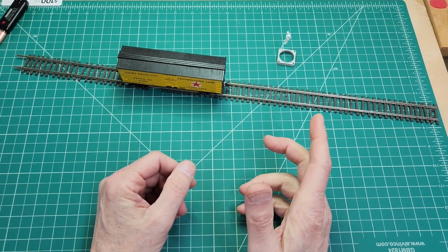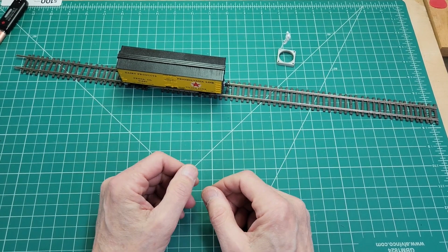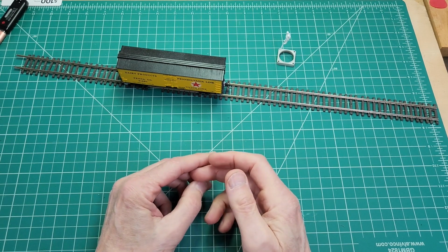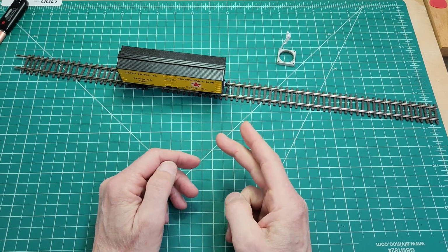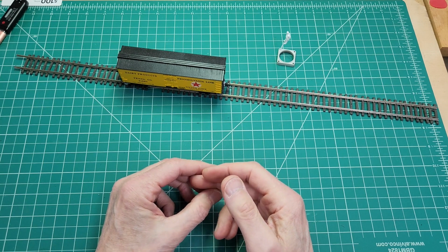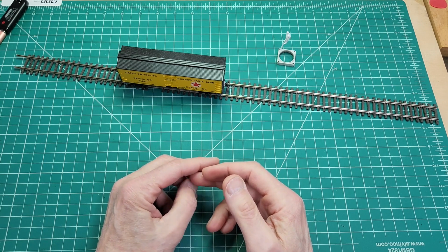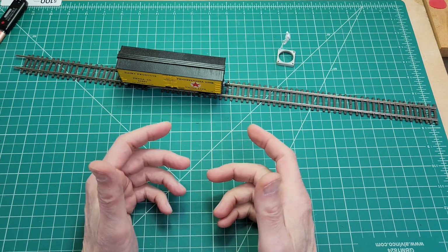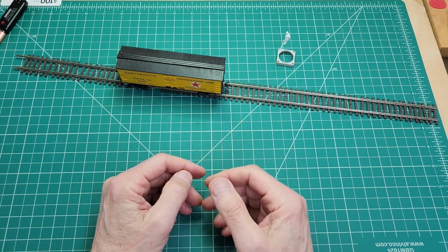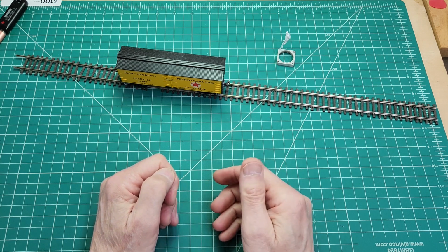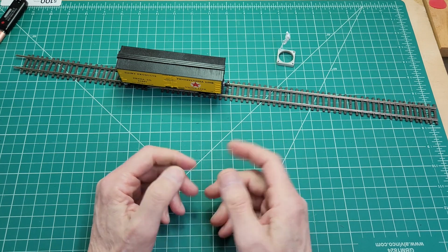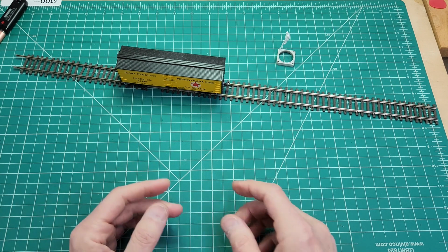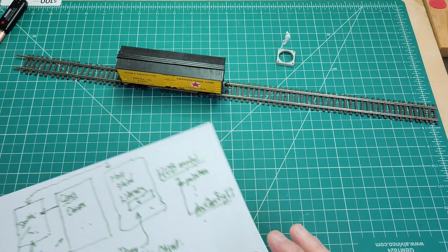The host shield library depends on a number of callback methods in the driver class, my driver class. And my class currently implements only 2 of these callbacks. One is the endpoint extract method and the other is init. And there are others that the library would like to call, and I just didn't need them. For instance, the on init, pull, parse, release, and get address. Let me quickly diagram this callback technique the library is using.